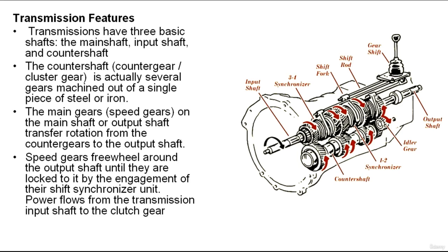The counter gear mounts on roller bearings on the counter shaft, and the counter shaft is pinned in place and doesn't turn. Thrust washers control the amount of end play of the unit in the transmission case.